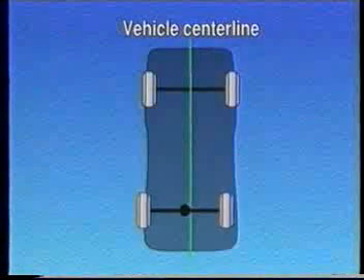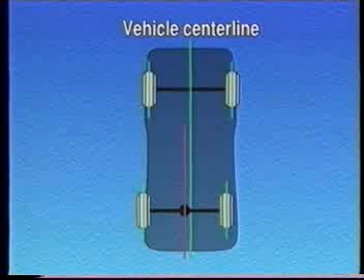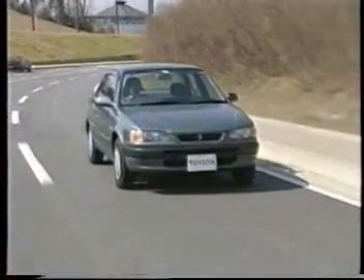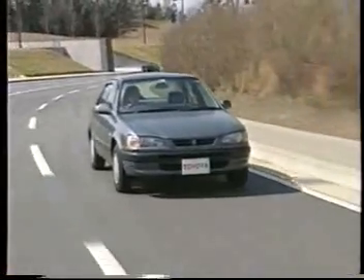Even if the axles are parallel, a lateral misalignment will lead to a difference in left and right cornering. So you need to be comprehensively sure that each of the four wheels is properly aligned to the car body. It is especially important to check the four-wheel alignment of a vehicle which has been in an accident.